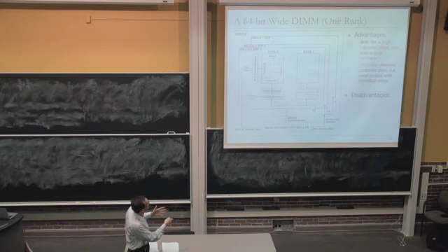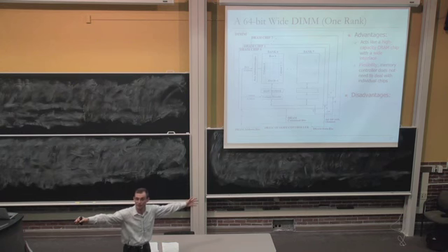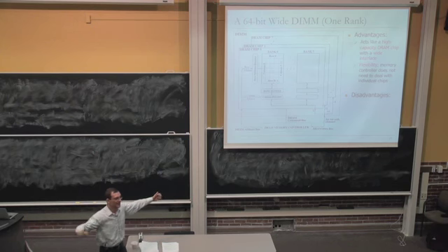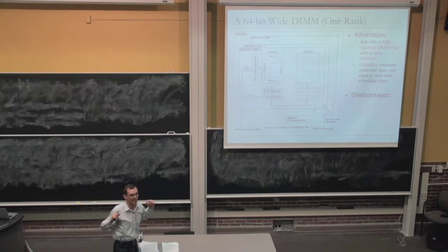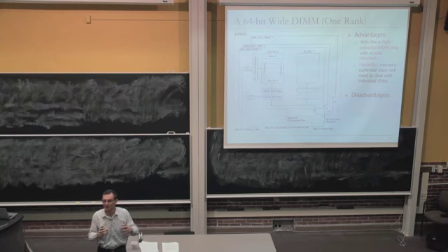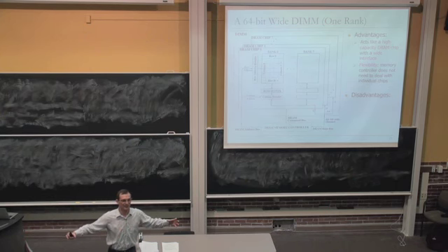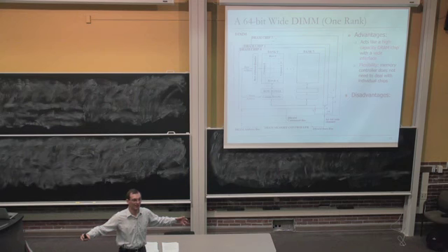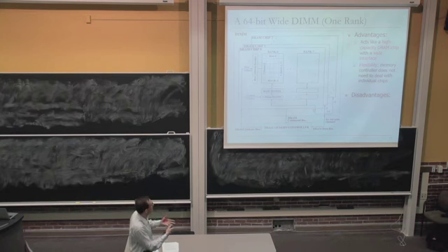I mean, you might want to actually put, if you have a chip that has 8 bits, you're getting 1 byte from each chip, and your cache block is 64 bytes, you might want to put 64 of these and control them at the same time, right? Such that with one command, you get the entire cache line, cache block. Now, there's a reason why this is not done, and the reason is pins, right? Pins coming out of the processor are very expensive. You can have 64 times 8, 512 pins, and we discussed this. That's very costly compared to only 64 pins. That's why what's done is you have 64 pins and read data in consecutive cycles.